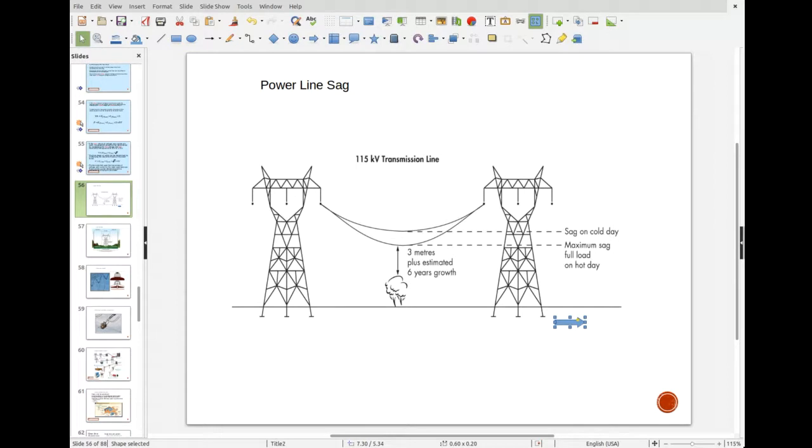All right, so we had one line go down for whatever reason, which means all the current that line was carrying ended up elsewhere, because people were still trying to use the exact same amount of electricity, whether that transmission line was working or not. And so all that current got transferred over to these other lines that didn't go down. Well, then another one went down because it started getting overloaded. And so we had this cascade effect.